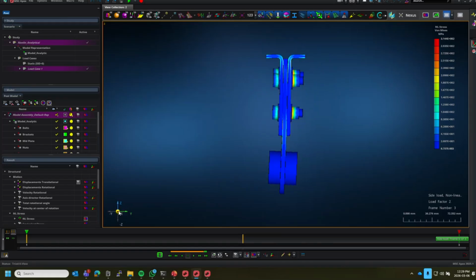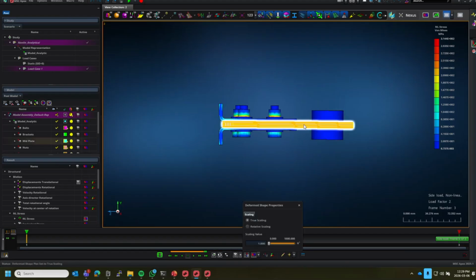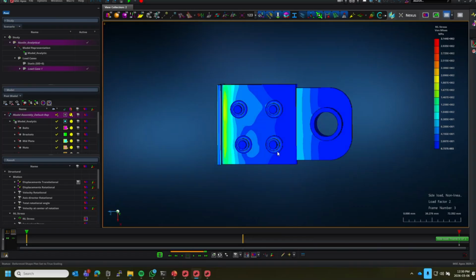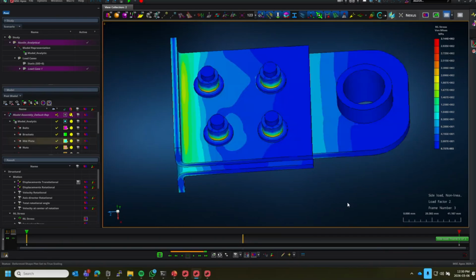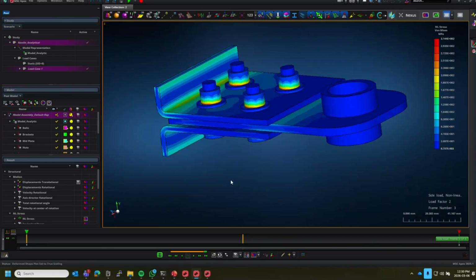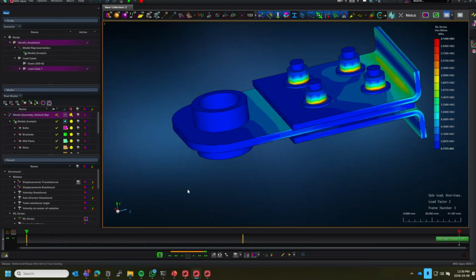Button, sorry. So there you can see it's been bent a little bit. If I plot it back to true scale, you can still see it's bent a little bit, but not crazy. Okay, so that's important for nonlinear analysis, to look at the loads in true scale for starters at least. Okay, but then the rest kind of makes sense. We expect to see higher stresses there than there. So in principle, the answer at least makes sense.